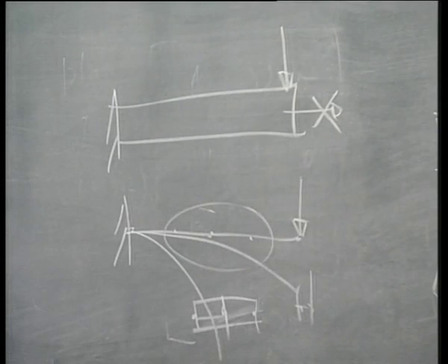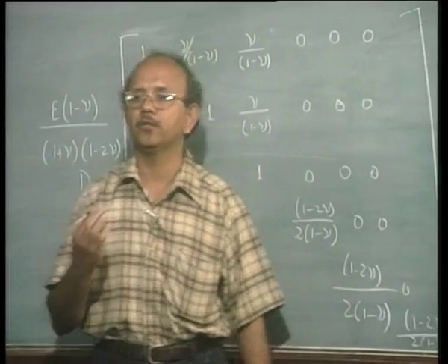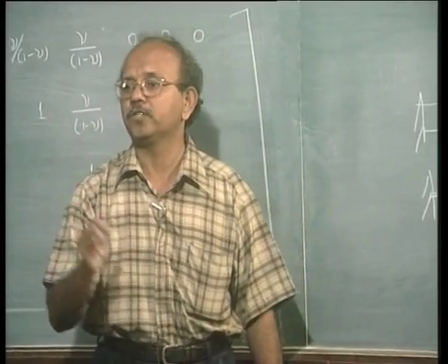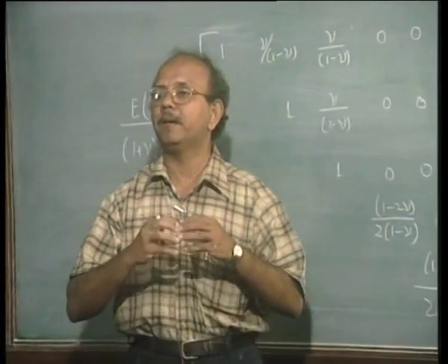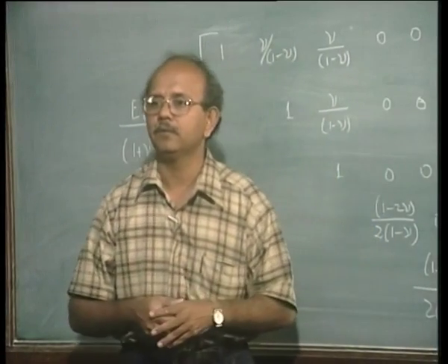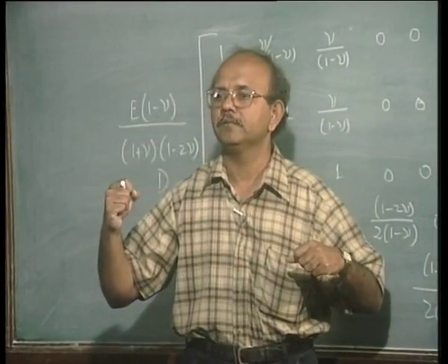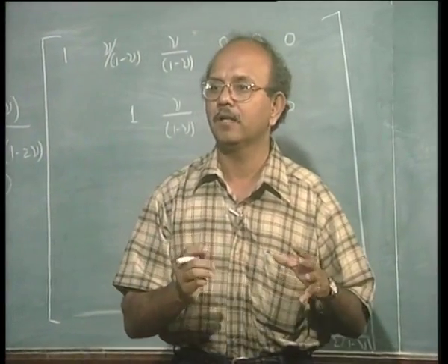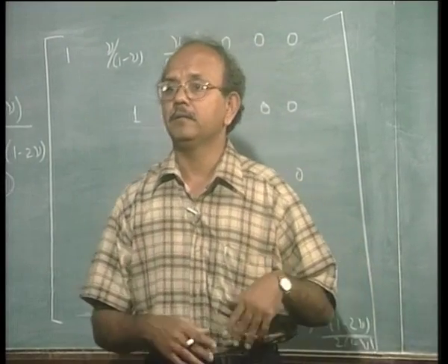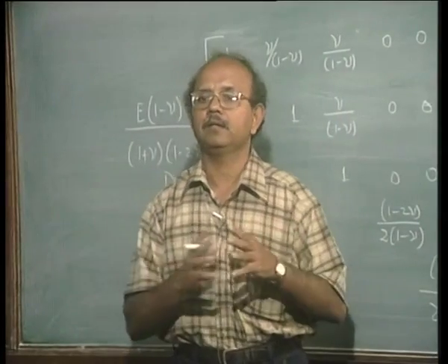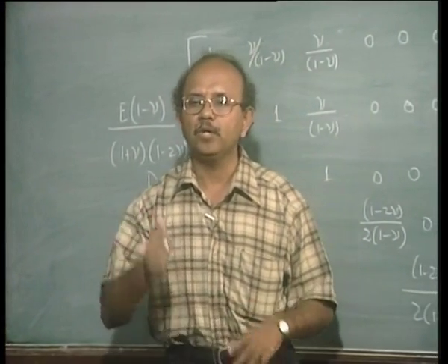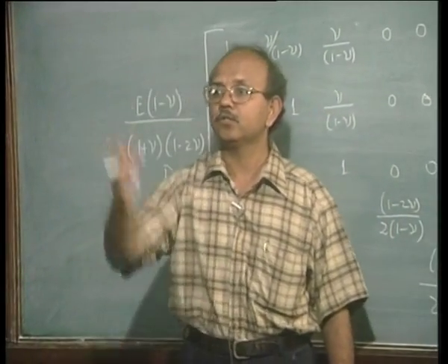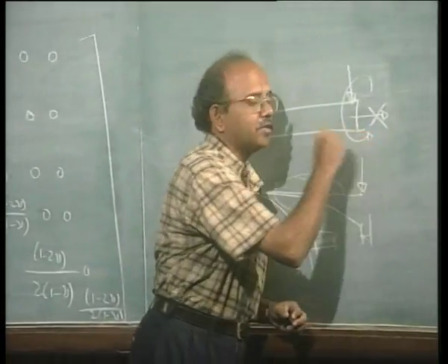So what should I do now? What do you think I can do now? We have studied what is to be done at that place. Superposition, very good. That means that if I can put the bar property along with the beam, introduce one more degree of freedom, and for that degree of freedom put the corresponding stiffnesses, then I can simulate both the beam as well as the bar type of behavior. Only one is remaining. Still I have not completed the case. What is it? Twist. So there can be a torsion.